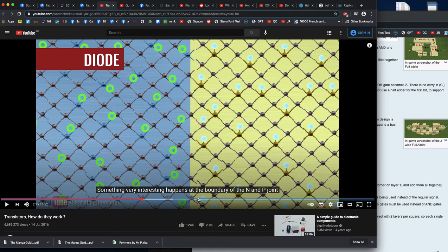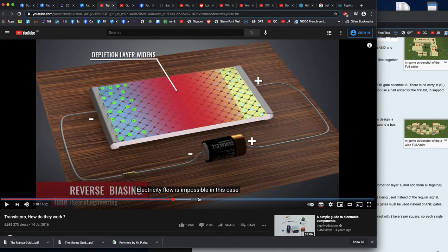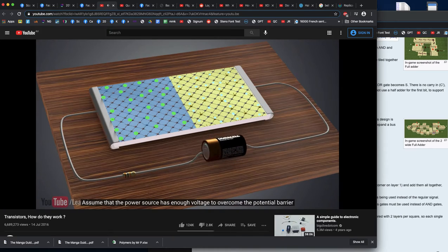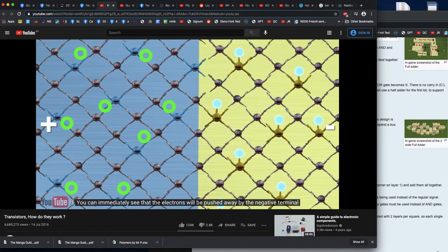Well, a diode is where we just have 2. We just have an N-type and a P-type. And in that situation, they will not allow electricity to move. Those holes, they'll get stuck. So a diode will only allow electricity to move in one direction. If you reverse the power connection, the situation is quite different. Assume that the power source has enough voltage to overcome the potential barrier. You can immediately see that the electrons will be pushed away by the negative terminal. When the electrons cross the potential barrier, they will be drained of energy and will easily occupy the holes in the P region. But due to the attraction of the positive...